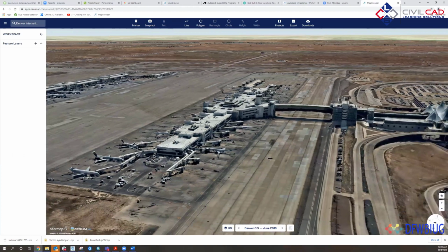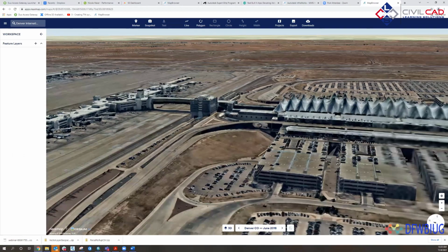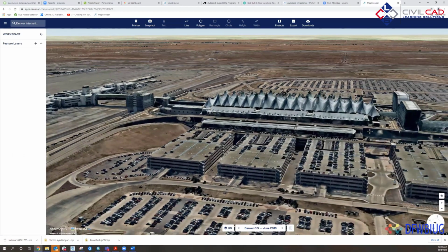Now, let's talk about the two different methods of taking the aerial and bringing it into Civil 3D. I know there's two methods. One is you can just go through the browser and download the GIS with the world file of the site, and the other one is creating a custom service WMS connection. Correct? Is there a third option? I don't know, I think those are the two most common ways. Yeah, within Civil 3D, it's either downloading it from Map Browser or the WMS.